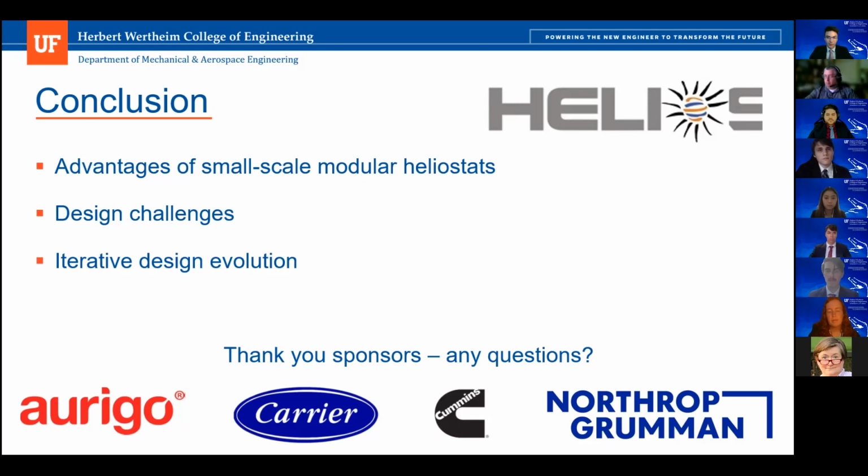The small scale of our heliostat design allowed us to use a simple drive system, reduce maintenance costs, and increase durability. The main challenges we faced were the field design and the material cost. The layout of the field was complicated because the sun shifts position year-round, and the direction of the modules and optimal field shape was eventually determined by using third-party software to compute the optimized position based on the sun's location.